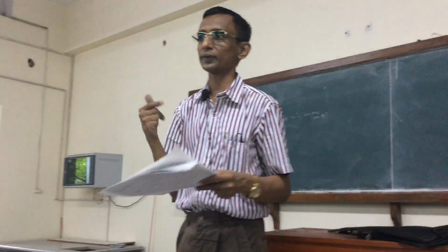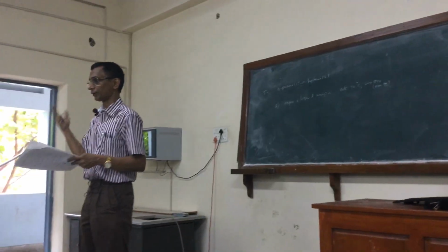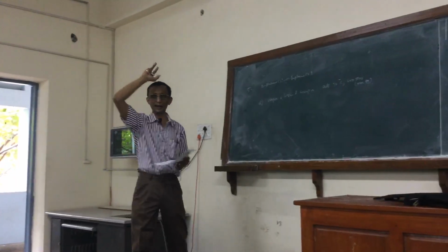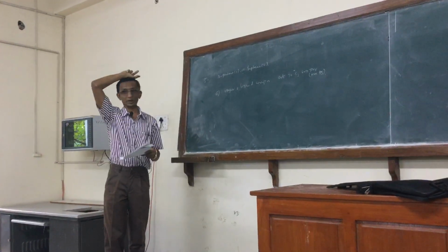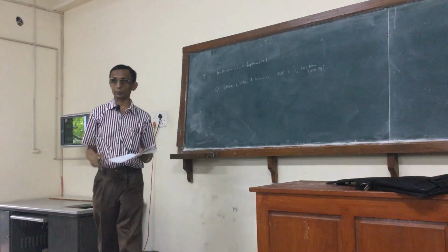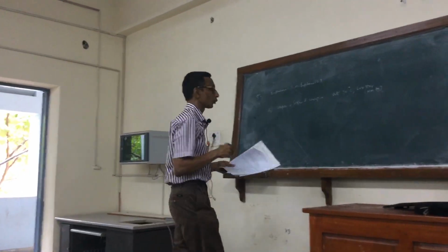Because Antoine's equation gives it in terms of this, normally it's convenient to use this and not Pascal and bar and all that. But you should know how to convert it. Standard is 760 torr. 1 torr is 1 mm Hg. All of you know that 760 is 1 atmosphere, so you can easily convert to bar, atmosphere, Pascal, whatever you want.